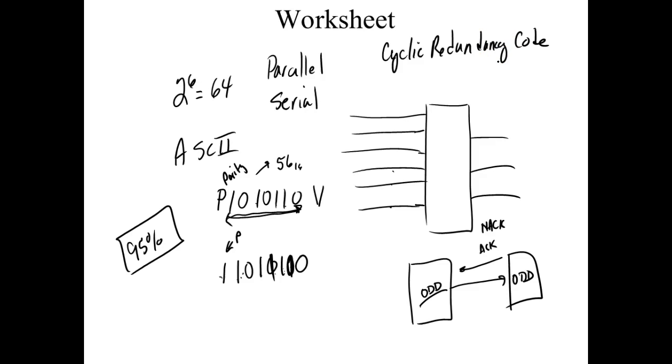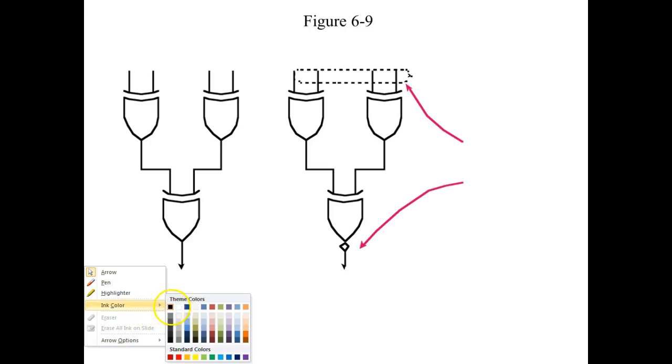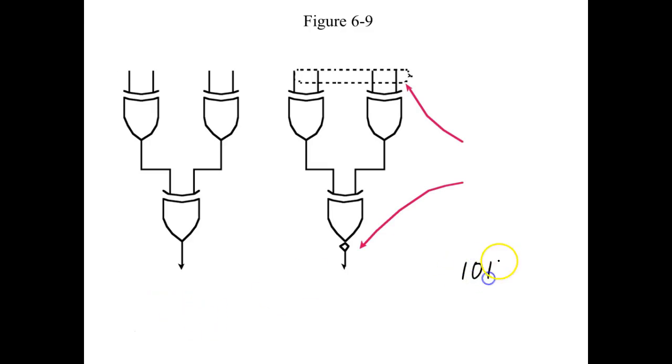But we're dealing with parity. So what they had to do is come up with some type of circuit that would automatically generate and detect parity, or equality, right? You understand that? So guess what they use? They use parity generators. So what we need to do is just come up with a 4-bit number. This is what I'm trying to send, and then we're going to add another bit up here that we call the parity bit.